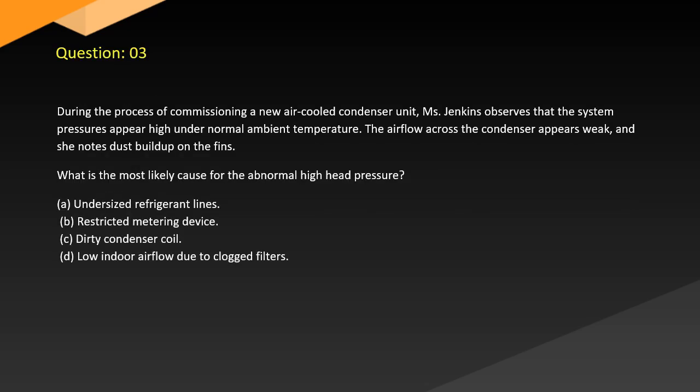Question 3. During the process of commissioning a new air-cooled condenser unit, Jenkins observes that the system pressures appear higher than normal for the ambient temperature. The airflow across the condenser appears weak, and she notes dust buildup on the fins. What is the most likely cause for the abnormally high head pressure?